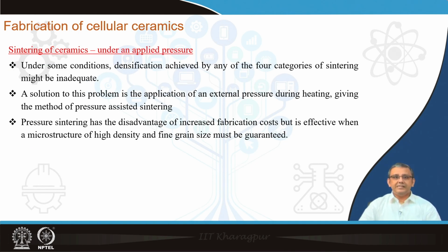Now, all these processes which I have mentioned until now, the solid state processing or liquid state processing, are typically fabricated under no applied pressure, that means it is pressureless sintering. But there are also processes where some extra pressure is applied to accelerate the densification process, and these processes are known as sintering under applied pressure or pressure assisted sintering.